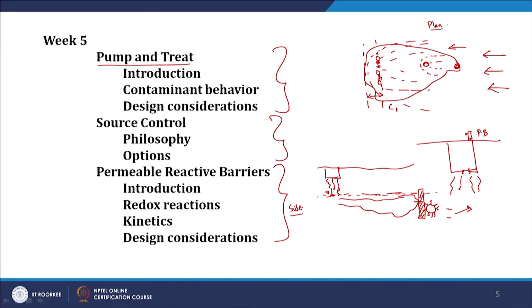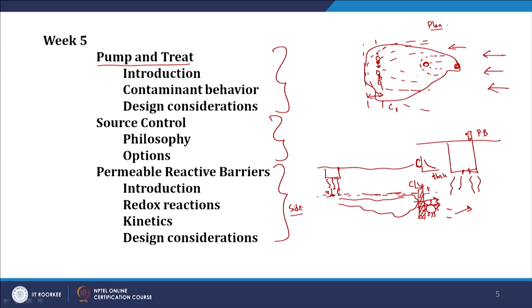As the contaminated groundwater passes through the barrier and then leaves it, considering the kinetics, if this is C versus T, or rather the thickness or length of the barrier, it is going to be a plug flow reactor. So the concentration is going to decrease as the contaminant moves through the barrier. There are obvious advantages here, as you do not need continuous operation and maintenance.